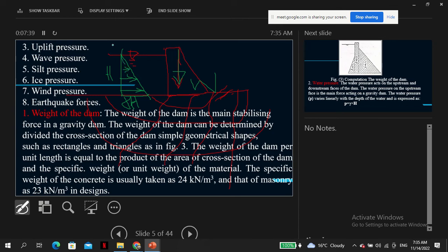So this is the water pressure we've talked about. The self weight of the dam, you can see obviously. Uplift forces, because water would want to flow there. I think we already talked about this, and we already even knew how to estimate this. You remember, you can get the pressure distribution here. You draw, for example, the pressure distribution there, and the head loss somewhere there.